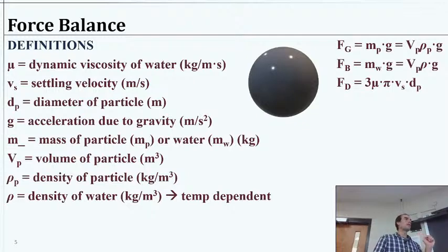So what's much easier to do is to find the bulk density. If you were to use a filter to separate those particles and then weigh a whole bunch of them and compare that to how much water they're displacing, so what volume of particles versus their mass, that's much more possible. And you can get some idea of how dense the particles are. There are some other ways to do that, including sedimentation, where you could just make some observations to check. The other thing that's pretty easy to do is to measure their size. So we have pretty cheap, reliable methods to get a good estimate of how big these particles are.